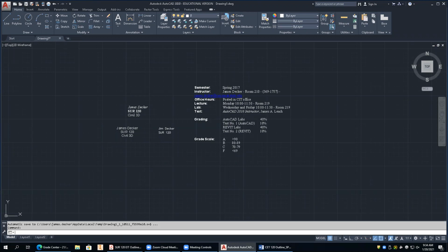If we go to this first piece here, this is showing you your A-size title block. Here's something to keep in mind too, and I'm real picky on this. If you have this border already in, you don't want to draw this line there, because that line is going to go on top of the other line, and then you're going to have what's called a duplicate object. I don't want any duplicate objects. I'll be looking for that. But basically, you're just going to offset, offset, offset, offset, offset, offset, offset, trim. You've got that thing knocked down. All of this line work is on the border layer.